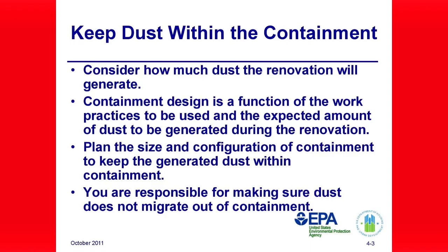Examples of dusty jobs include hand scraping large areas, removing paint with a low temperature heat gun and scraper, removing dry residue and paint after using chemical strippers, demolishing painted surfaces, removing building components with painted surfaces that are in poor condition. Remember, you are responsible for making sure that dust and debris remain inside of the contained work area.